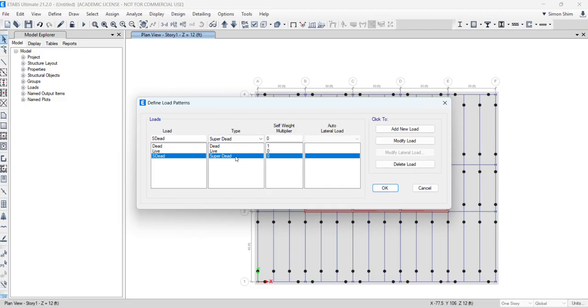And the superimposed dead load we've discussed: the building needs more stuff on top of structural elements, like ceiling, duct, and lighting, and then floor finish. This kind of load is attached and fixed, but it's not a structural element, so we can assign it as a load.